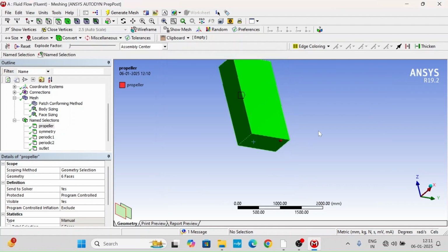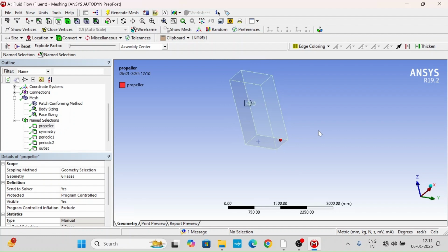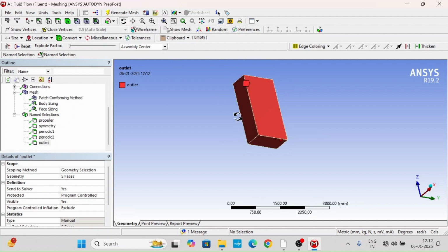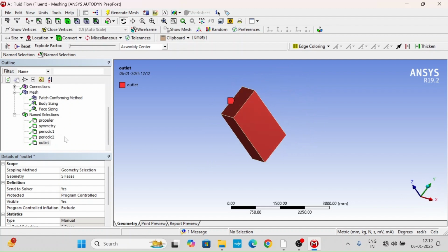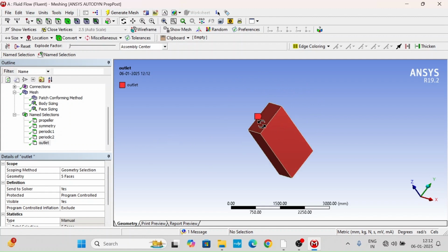This approach gives us something much more realistic, close to what we would have done using the same propeller in the physical environment. Every outer face of the body is set to outlet, which means it is connected to atmosphere. With this we don't have to give an inlet velocity at the inlet, so it's a much more realistic approach.